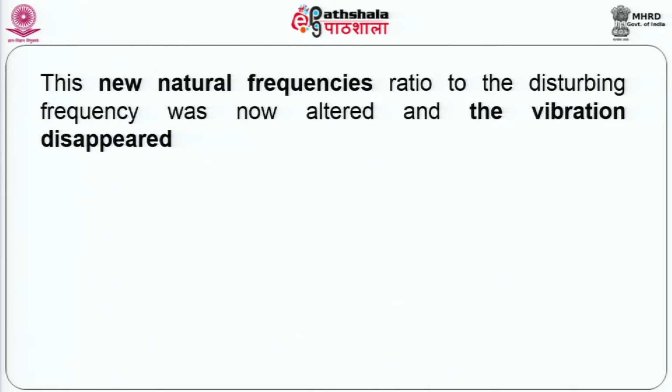So, by putting a device like a rubber toy, one altered the static deflection of the media and changed the natural frequency of the structure. Suffice it to say that even a building of 10 stories, 20 stories, 50 stories has a natural frequency. What disturbs this natural frequency must be a disturbing frequency, and the disturbing frequency and natural frequency must be far apart from one another. Otherwise, if they are very close, they will suffer resonance and the building can collapse. This rubber toy played around with the static deflection, developed a new natural frequency and attenuated the vibration.